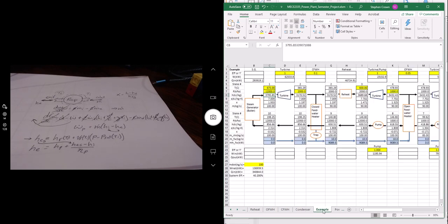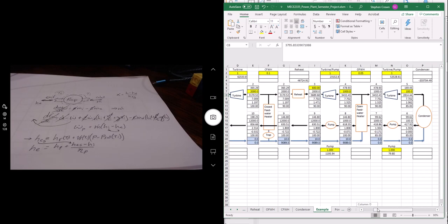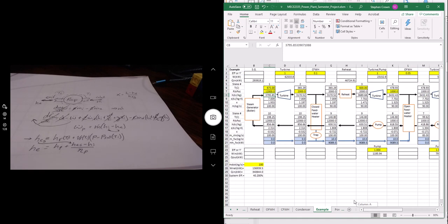All right, so I hope this is helpful. Make sure you understand the equations for the pump and how we're doing this with the spreadsheet. And I'm hopeful that you'll enjoy building this very complex analysis tool, after we build all the components, for designing very complex power plants in a very short time. Once you have these components, you can build this complex system in about 30 seconds.